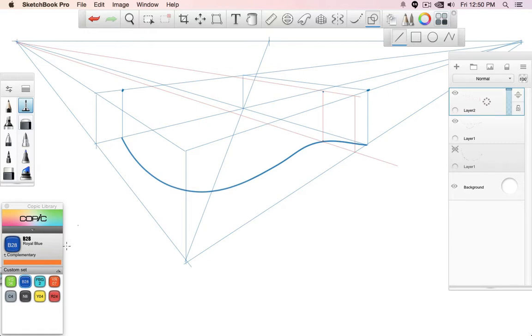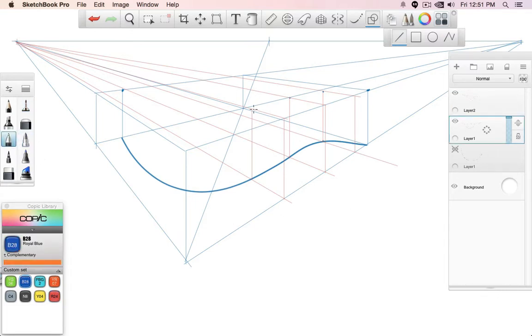Then let's make another one. So maybe let's say here. So going up, going back, going up, and there it is. Okay, next one. So you see a shape like this one to accurately project over actually requires a lot of construction planes and lines. And again, just don't eyeball it, don't trust your eye. Specifically when you're new to drawing, your eye will definitely fool you.